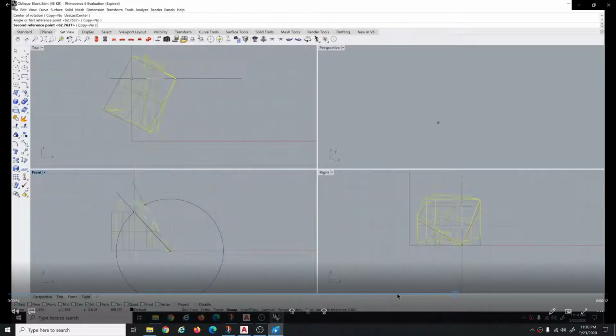The vertical height stays the same, and the right view is staying the same horizontal distance. Okay, that's just what happens when you do these rotations on a 3D object and you look at the orthographic projections. So that's the theory or the concept of why this thing works.